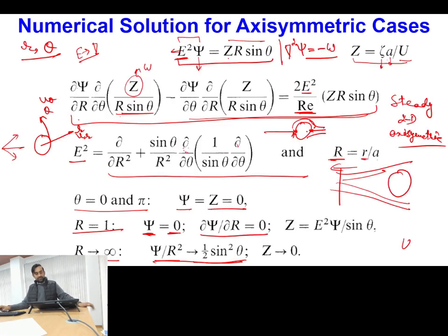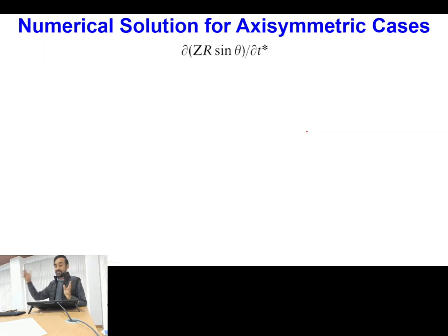Now of course, this is the system of equations for steady flow, and whenever my interest is only to see the final steady velocity profile of the system, then I will be solving this system of equations. But if my interest is to know how the flow is actually evolving before reaching the steady state, then I will be interested in a time marching solution.